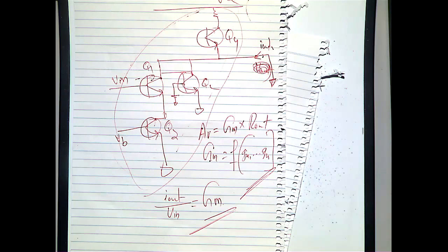And then for the exam, if there is a question, find out the voltage gain of the below circuit, then you are welcome to use just small signal or short circuit transconductance. But if the question is find out the gain of the below circuit using short circuit transconductance, it means you have to use this technique. Then you have two tasks: find out the capital GM and then find out Rout, the output impedance. So usually we ask a question from the short circuit transconductance.